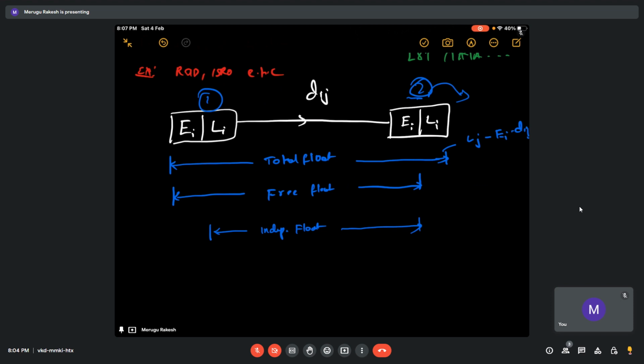So this is just a diagram that you can remember. I will explain it. This is just if they give these two nodes. Suppose for event one, I have say 7, 10, with a duration of 5, and event two I have 7 plus 5 always 12, then I have some 17 here. 17 minus 5 is 12. Okay, these are the timings I have available in my network. So now, what is the total float?